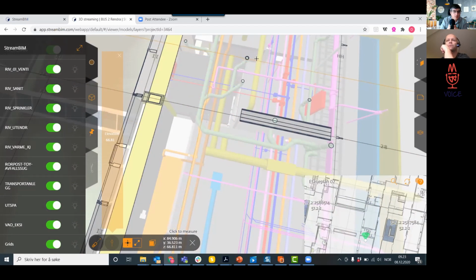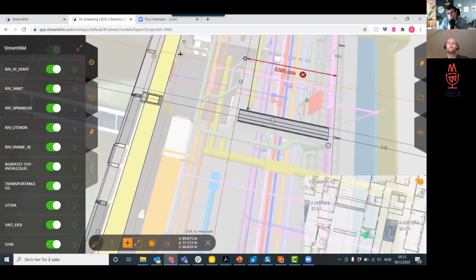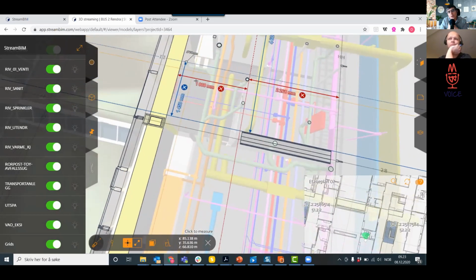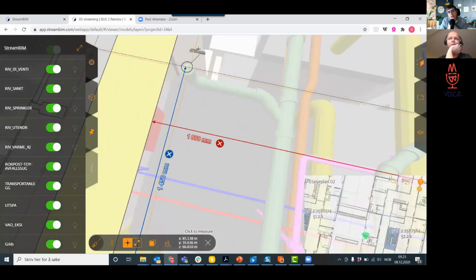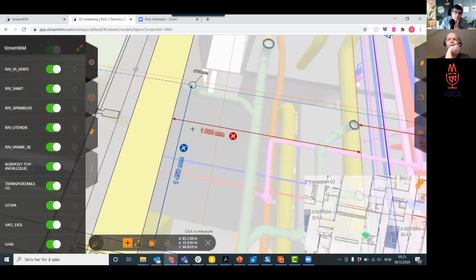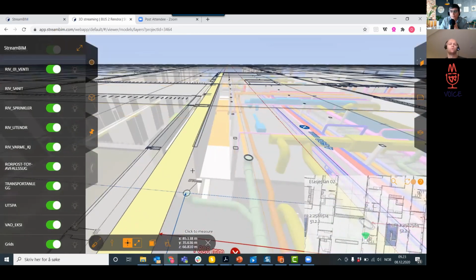But you want to measure sometimes also for this pipe. Where does this come out of the concrete? So it snaps. It snaps also to the grid lines automatically. Yeah, snap. So this is laser measurement. And as you can see, it goes to the center point of the pipe, and it also lists the diameter that you're hitting here. So this hospital project of 50,000 square meters is produced almost without using drawings. They just use the measurements in the model.